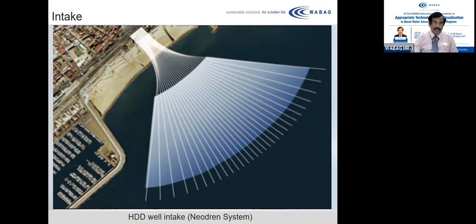This is similar to a seabed filtration arrangement. Only thing is this is drilled, and there you have to cut a big pit, put the pipe galleries, and over which we have to put a gravel, and then fill with the sand medium. So this arrangement, along with the other arrangement which I told about, the galleries, has to depend on the permeability of the soil in that zone.